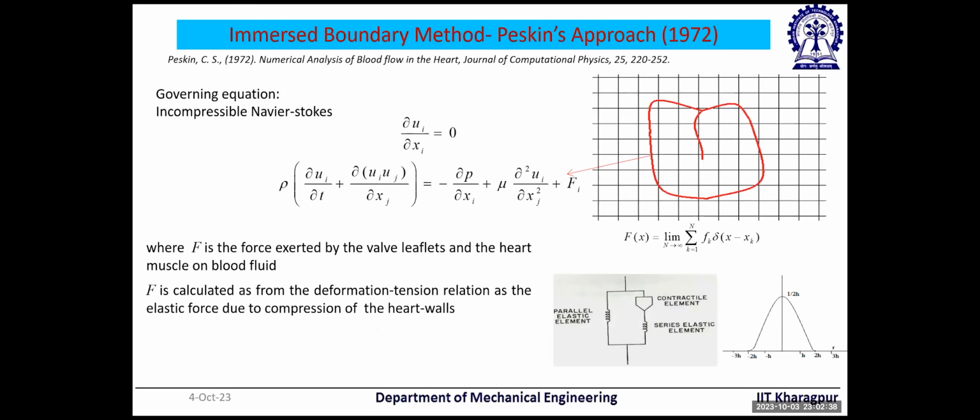The immersed boundary method is one of the approaches in CFD simulation in which flow over moving and deformable geometry can be computed using a general Cartesian mesh framework. So in the background, we use a structured Cartesian mesh without considering the movement and complexities of the geometry. Now the difficulty is how to impose the boundary conditions. In order to do that, we identify the